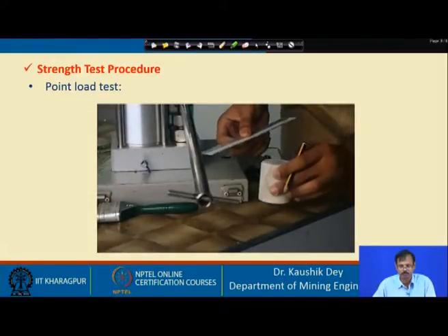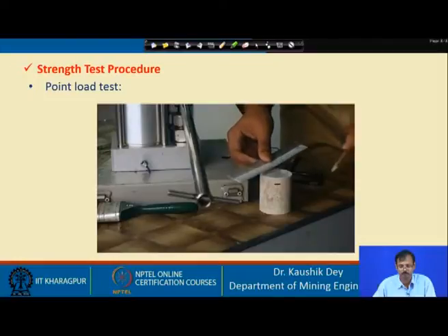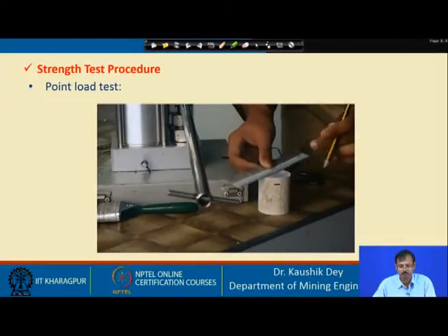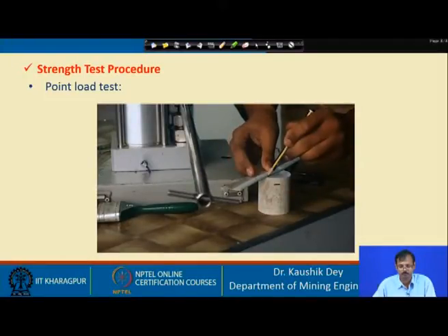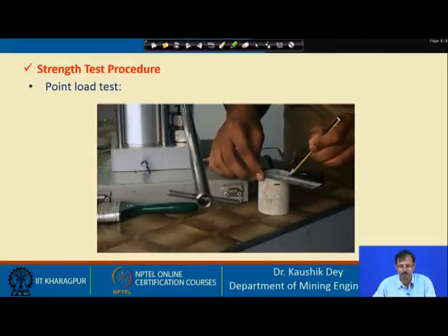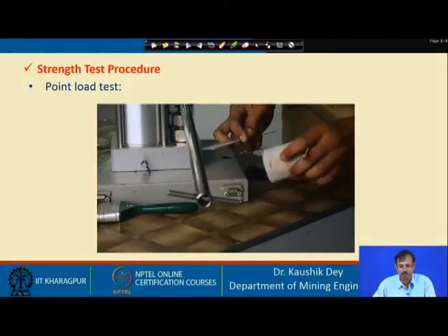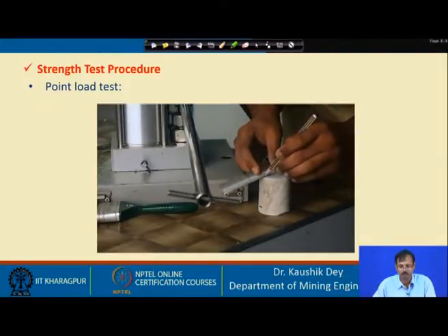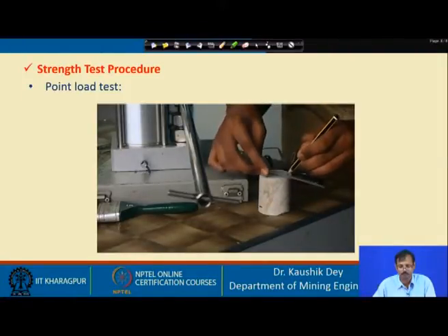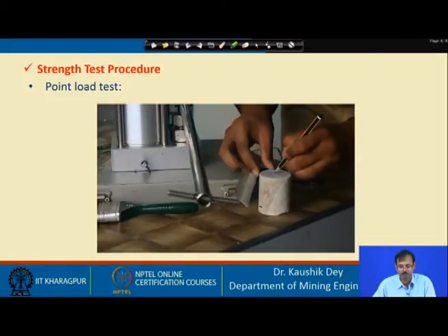The test starts with marking the center point of the samples. By using a pencil and ruler, find the midpoint of the top sample based on this cross-section line, and do the same thing to the bottom one. This is important in order to get a good result and true mode of failure.